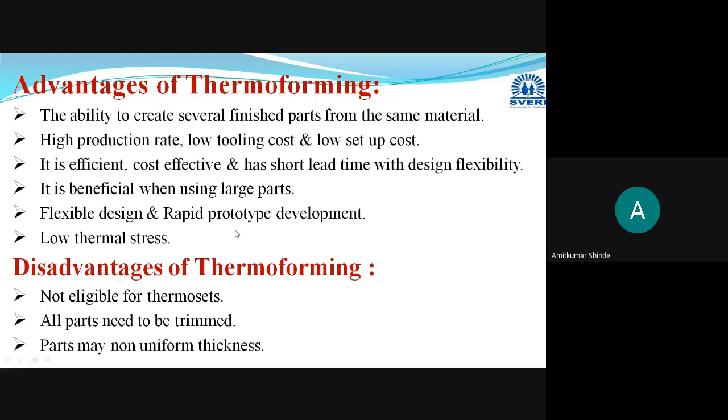And as here we are performing a heating operation and then applying the pressure, thermal stresses will be very less. The temperature range is not so high, it is below 200 degrees Celsius, and first we are heating it and after that applying the force. Due to that, thermal stresses are very less. So these are some advantages.